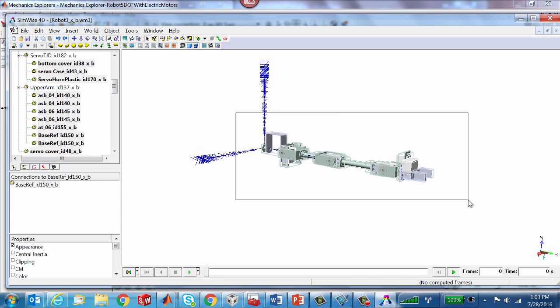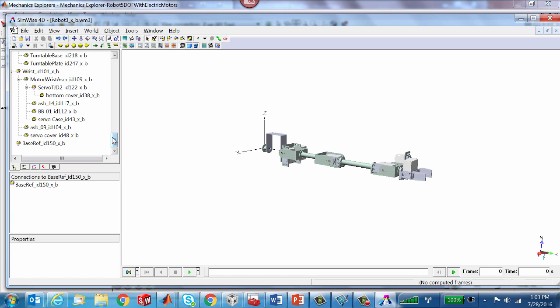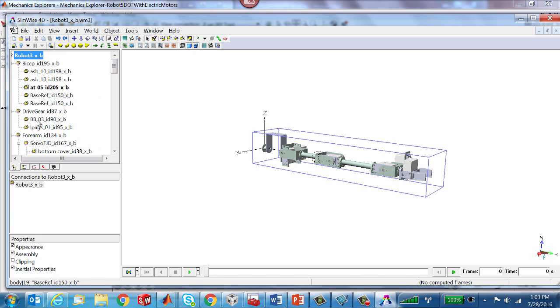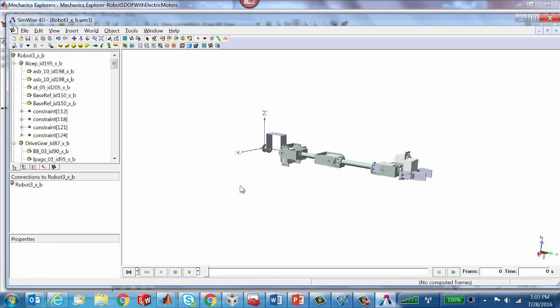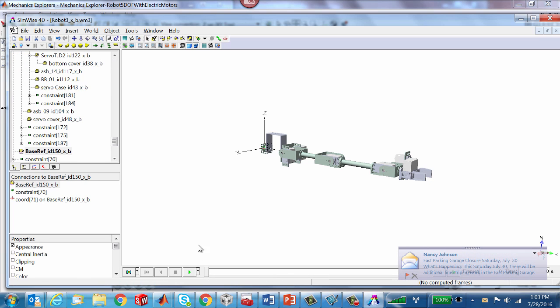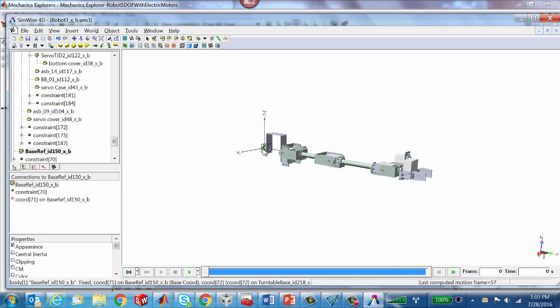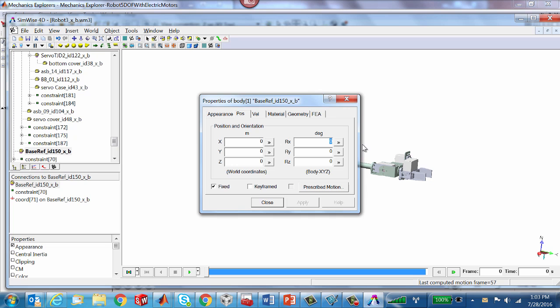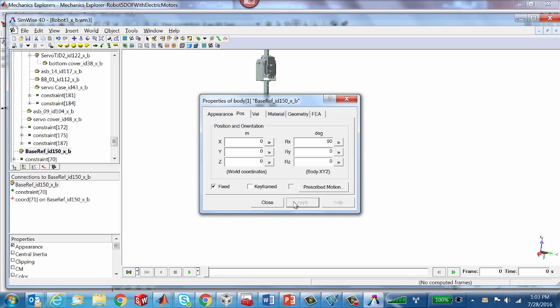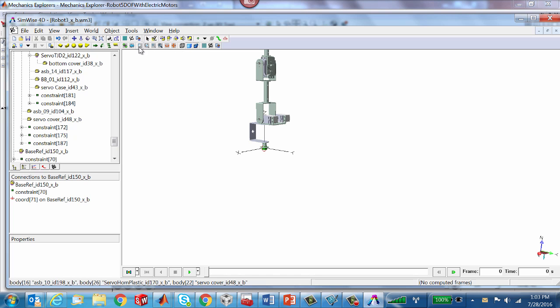This time, I want to select basically the whole assembly. For many reasons, it's good to start working with this list. We're going to see a hierarchy of sub-assemblies and all that kind of stuff that was defined in Siemens NX, and it's defined in pretty much every CAD tool. I'm going to do something called rigidly joined bodies. This is really a trick I'm showing you right now. Because this whole assembly is now connected, when I hit run, it doesn't fall. It means I can take this part and rotate it 90 degrees and hit apply, and the whole assembly rotates.